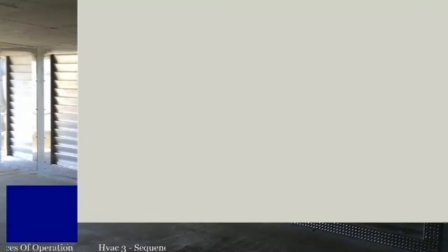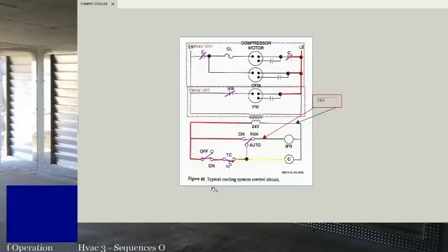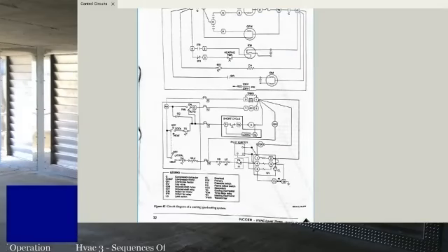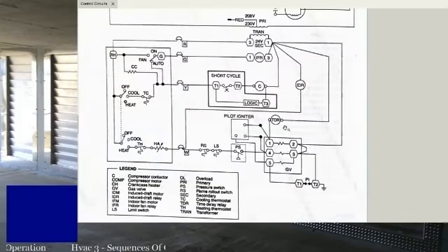With that in mind, let's go to 3.2.2, heating sequence of operation, for a minute. Because with furnaces, understanding the sequence can usually narrow it down to a single component really fast, because everything happens in sequence on a furnace. So once we've ruled out all our basic stuff again, once we've ruled out power, voltage at the thermostat, and so forth, if we're looking at a furnace sequence, then once it starts its actual ignition sequence, we'll know what's going on with the furnace.